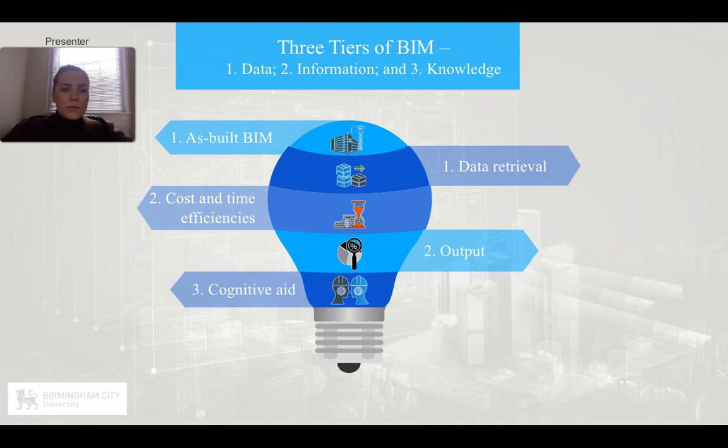To give you a simple example, when a contractor is doing a clash detection, for instance, instead of relying on a standard template to perform a clash detection on a particular type of project, they may use previous knowledge and insights from a previous project of a similar nature and conduct the clash detection based on tolerances that they think are most feasible and suitable for that type of project.